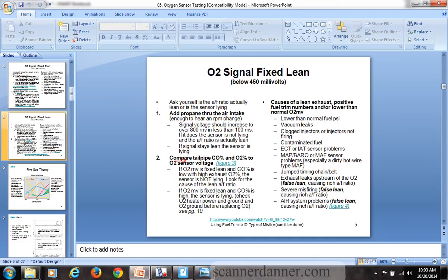That one works perfect. There is no variable I can give you where you cannot fuel the engine enough, like we can't lean it enough. I gave you that example, but in this case, I'm good with this test. Will the flood or the gas pedal one work here too? Can we do the gas pedal test here as well? Yes. And can we look at downstream O2s? Use those as a guide.